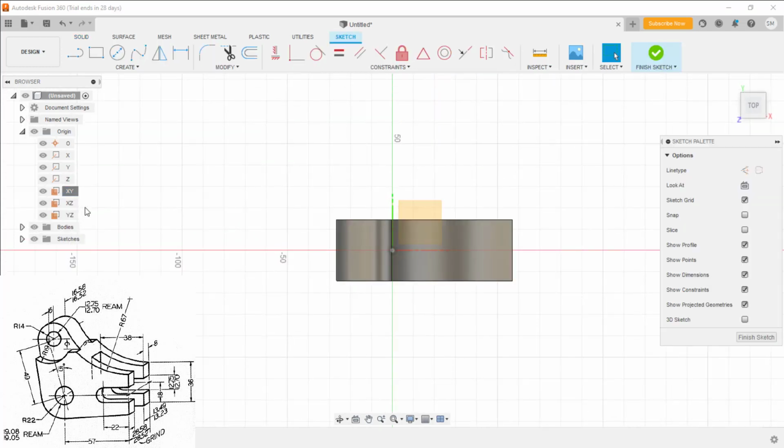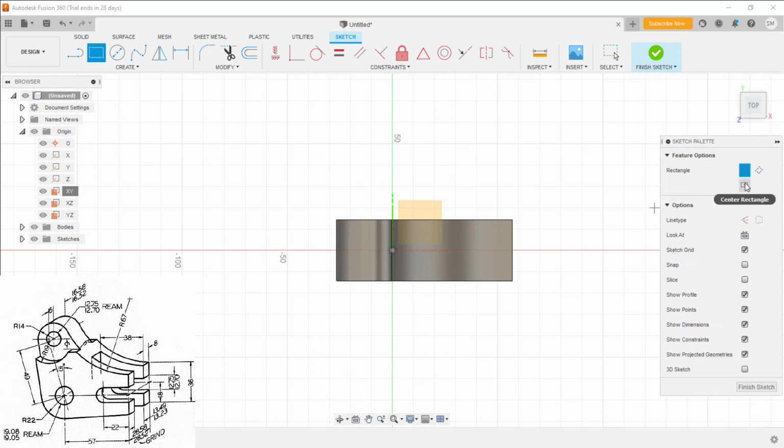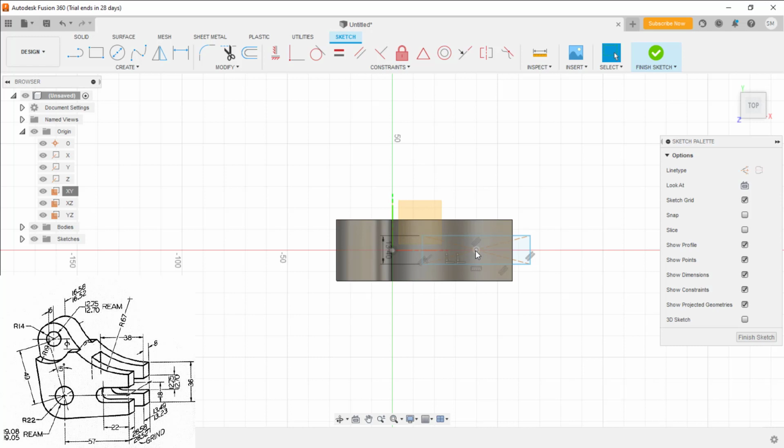fine. So I'll select the top plane. On this I'll sketch a center circle. I need the shortcut S, center circle, switch to that. Yeah, dimension, you could see there the gap is given as 13.4 or 2, you can refer to anything. Now from these two, make it horizontal. Automatically it will snap vertical or horizontal depending upon the requirement. Between these two it is given as 38.